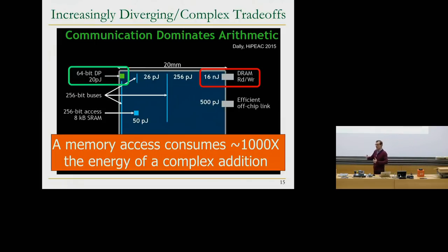There's also the law of technology scaling. It's called Dennard scaling. Bob Dennard is the inventor of DRAM in 1965. He was at IBM. He invented DRAM. He also developed a theory of transistor scaling, which said essentially, as you reduce the size of the transistor, over time it becomes more efficient.